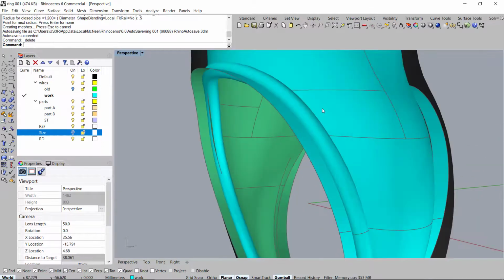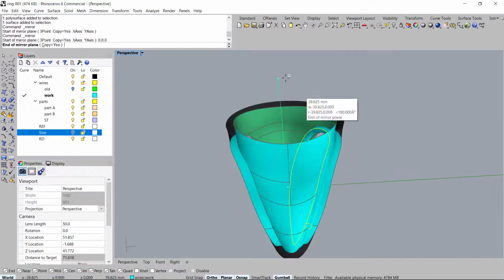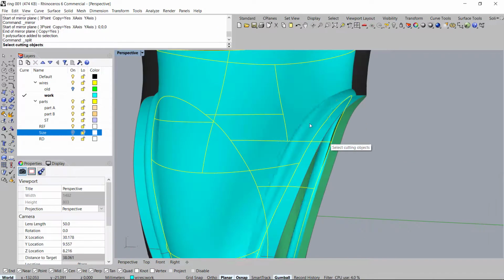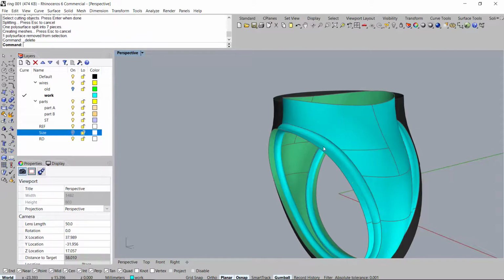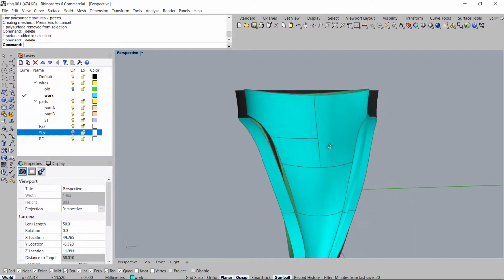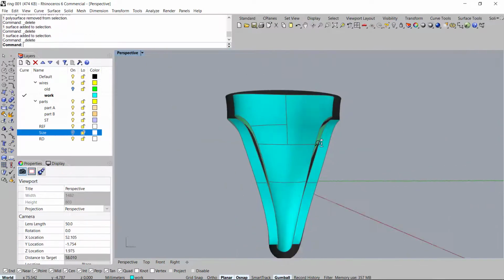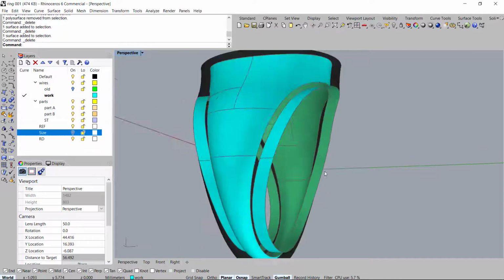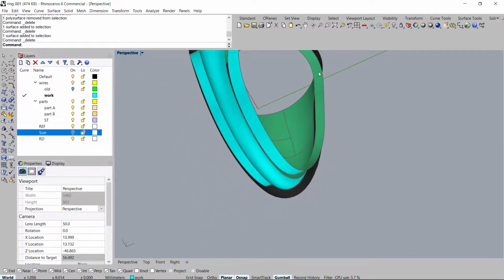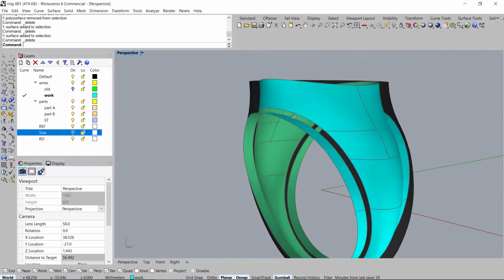So select this pipe, split it with the tube we just created. Yeah, see, it has a nice separation. That's perfect. Okay, you do not want to affect this width here. You want to maintain the 1.2 millimeter border. Okay, it's mainly for comfort.